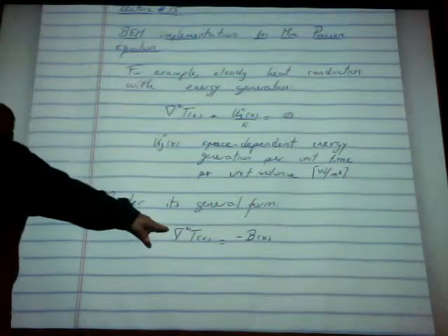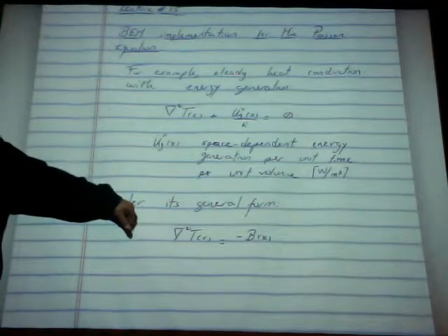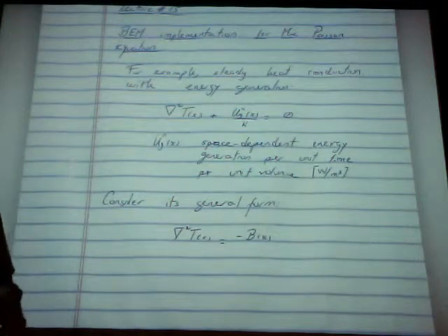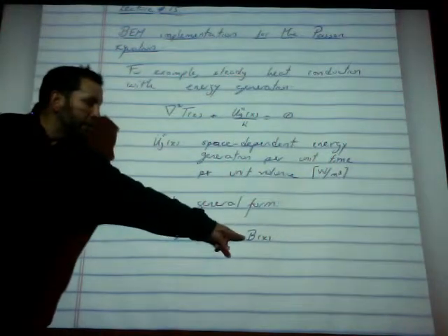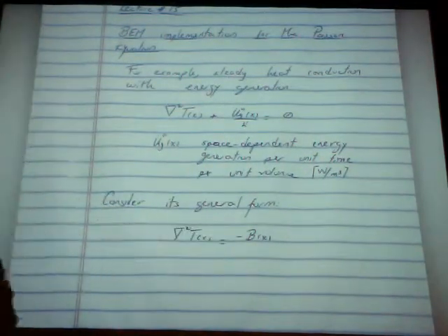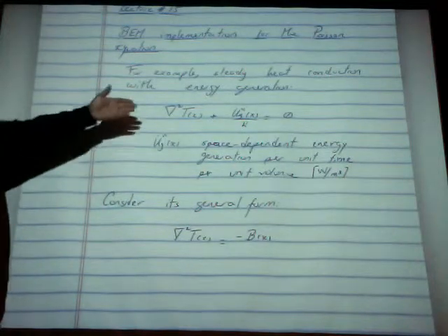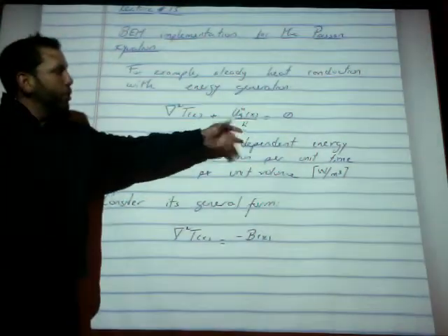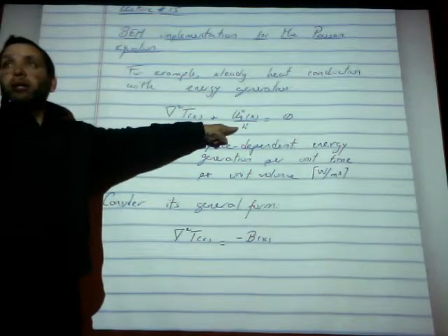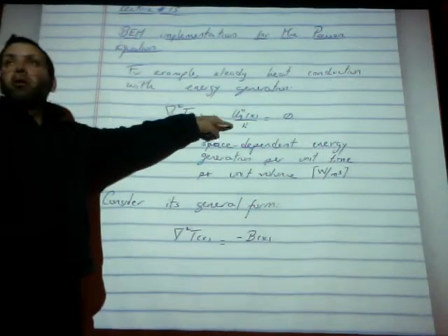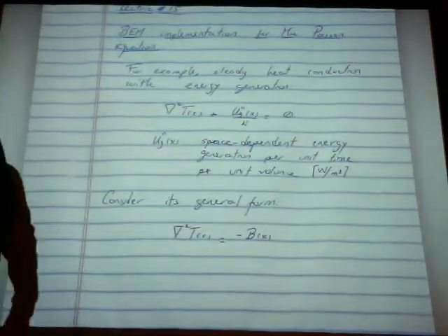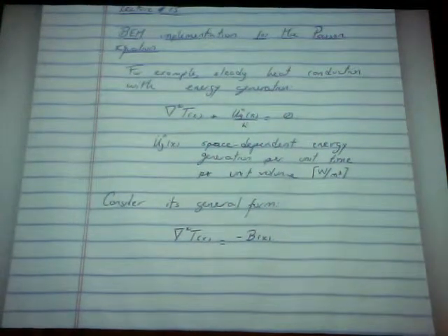What are the units of the Laplace? It's the derivative with respect to x squared, so it's meter squared, right? That's the units of the Laplace. So this has to be Kelvin per meter squared for these to be dimensionally consistent. And you can actually get it directly from here. UG is watts per meter cubed. Well, K, the conductivity, is watts per meter Kelvin, right? So the watts and the watts go away, the meter cubed and the meter go to meter squared, and the Kelvin goes to the top, right?